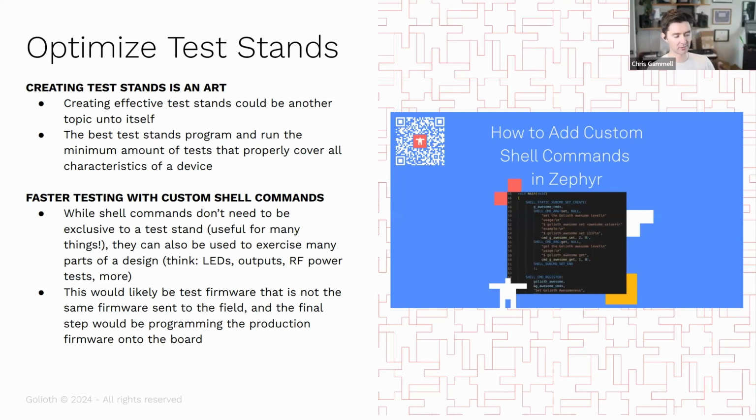need, basically the bare minimum to cover all of the functionality that you have on board, right? You might not need to send a Bluetooth packet to a secondary device to test that Bluetooth works, but you probably want to make sure that your device was at least assembled correctly and that you are able to output the power level that you expected, right? You can definitely test those sort of things, and then you rely on the firmware piece later to actually handle all the stack. So at the very least, you want to have a firmware image that's on the device in a test environment where you're just validating the output power, right? Maybe instead of an antenna, you shortcut the antenna, you are outputting some power level into a load and you're able to test that.